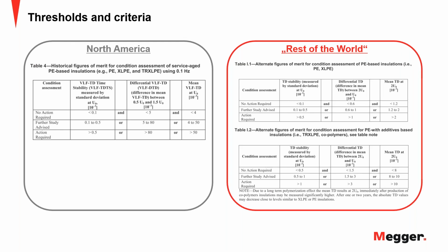That means people who typically run a cable replacement program prefer to do the tan delta test to help make that decision.